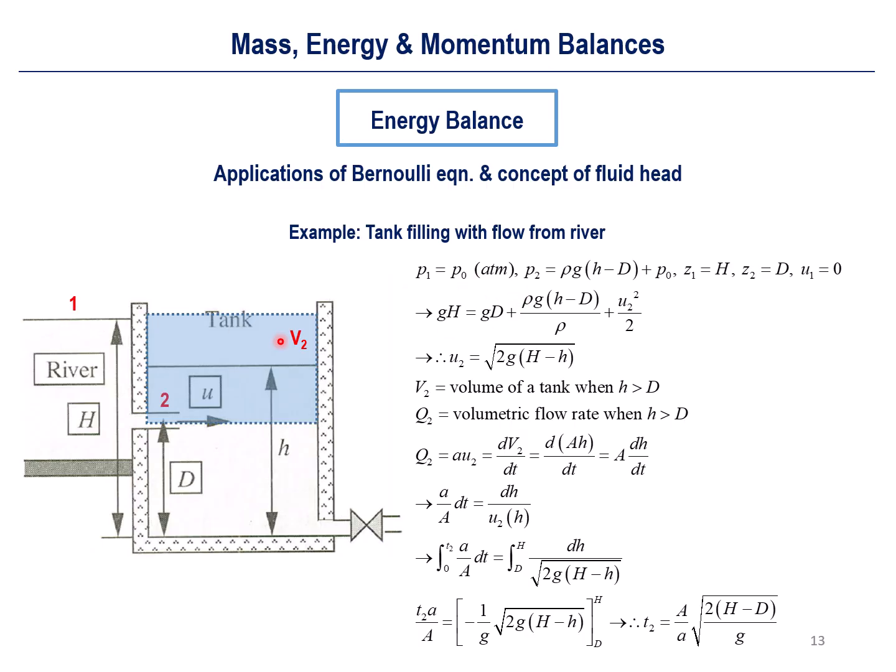But in these cases, point 2 is not exposed to the atmosphere, but is surrounded by water. So you need to recalculate the pressure P2, which is equal to the additional water amount, with Pascal's law, added to the atmospheric pressure. That's why we have additionally increased pressure here.